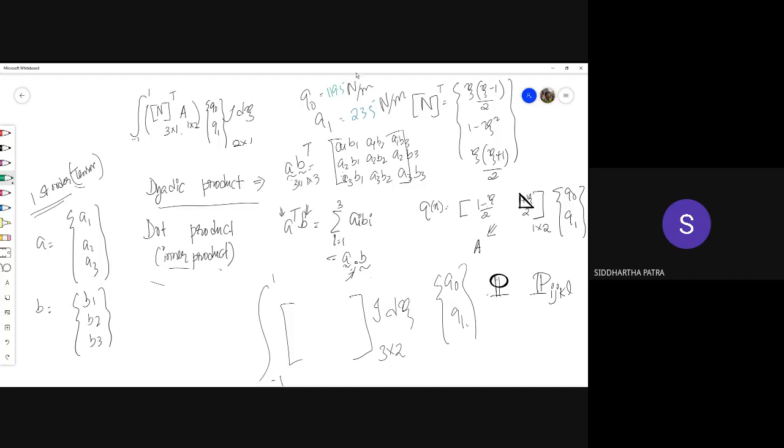Okay, you can keep them out of the integration, and you can simply integrate terms which are either 1, or half, or something like that. So that would be quite easier for you to do the integration. And for that matter, this j term also is a constant. The way we have chosen x2 to be x1 plus x3 by 2, that essentially gives you j to be x3 minus x1 by 2, or basically le by 2.